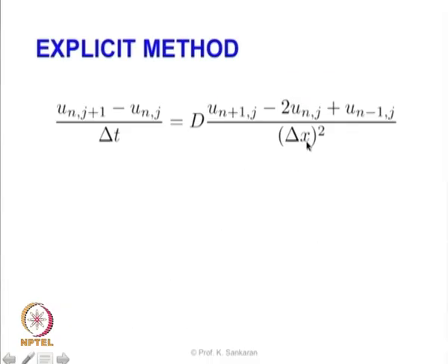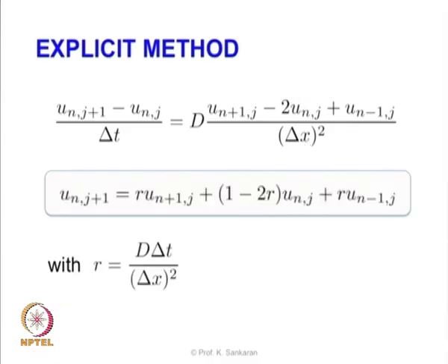the explicit formulation in such a manner that we set the value of R, which is going to be the stability criterion factor. We also said it's going to be twice this value that is going to be of interest for us because we have a 2R value, and I also explained why we have to take 2 times the R value as the maximum limit for the stability criterion. This explicit method, as we saw in the previous case, is going to have the disadvantage of going very slow in time stepping.